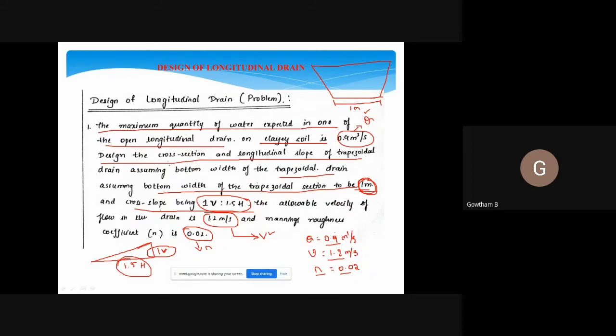Here he is saying that it is a cross slope or side slope. That means if I just put a dotted line here like this, you can see the diagram that I am writing. Suppose horizontal is 1.5. Here also you can take horizontal as 1.5. This vertical is how much now? We have to give slope 1.